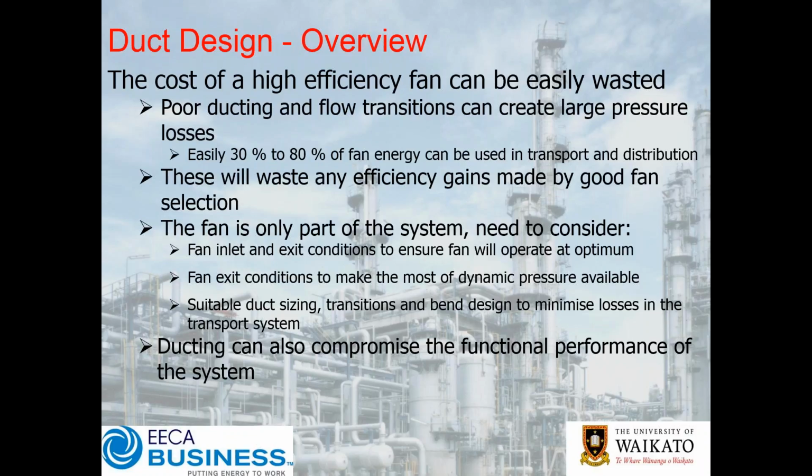The fan housing could be well engineered. Everything could be absolutely wonderful at the fan end, but if we then hook that fan up to poor ducting, poor flow transitions, and have generally bad flow through our process and various unit operations, the overall efficiency of the system can end up being very, very poor.